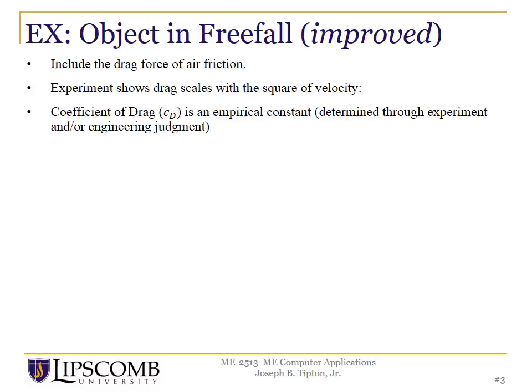Let's improve our model now by including the drag force of air friction. Now, air friction is a very messy thing in reality. You'll take several courses related to fluid flow in your mechanical engineering curriculum. A pretty good model that's also simple enough for us to use comes from experiment, which shows that the drag force scales with the square of the velocity.